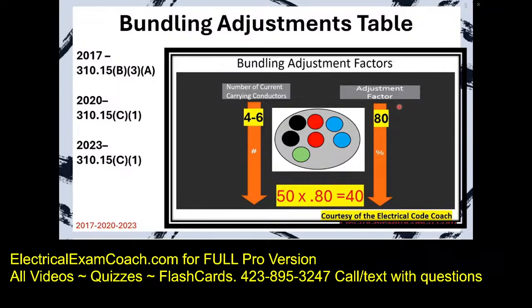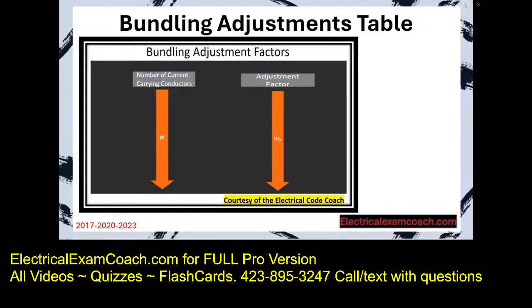What they're saying is that because of the number of wires inside of this pipe or cable, the wires cannot dissipate the heat safely. So you have to reduce how many amps the wire can handle. The new allowable ampacity of this wire is only 40 amps. Up until this point, we've had all hot conductors inside of our conduit. But what happens if we add in a neutral?